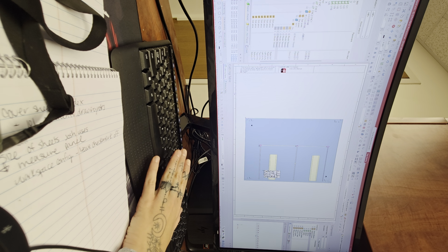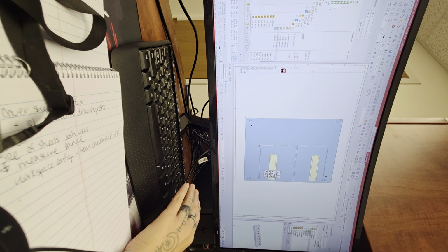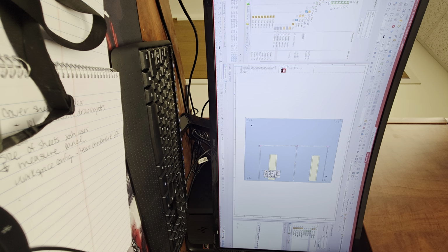Then you said I could do what in this preview? So you can left click in this preview, move it, so you can rotate this part as needed. Again, just purely to play around. Also in these preview windows, you can right click, and you can have predetermined views. So you can quickly do front view, side view, etc., whatever is needed in the moment. Just so you know, this preview window is more than just a screenshot kind of thing.